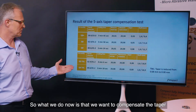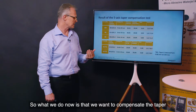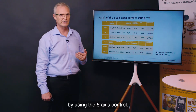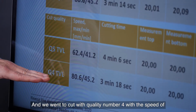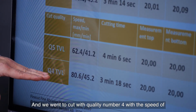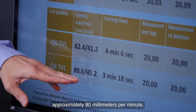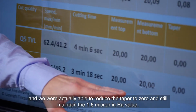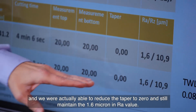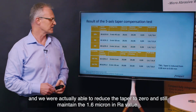So what we do now is that we want to compensate the taper by using the 5-axis control, and we went to cut with quality number 4 with the speed of approximately 80 millimeters per minute, and we were actually able to reduce the taper to 0 and still maintain the 1.6 micron in RA value.